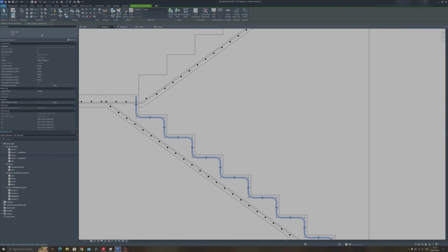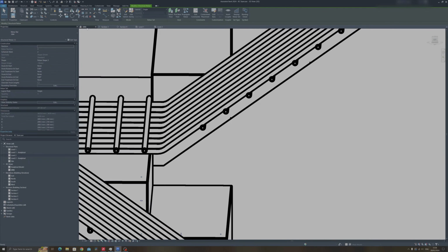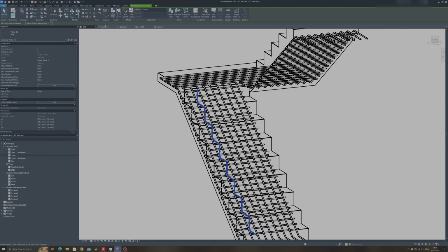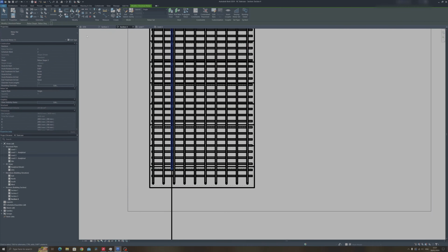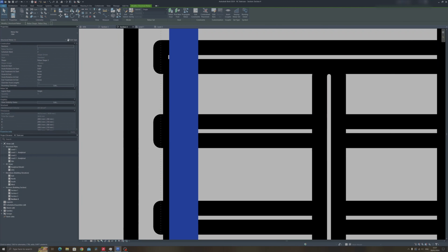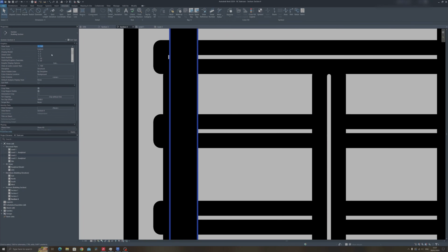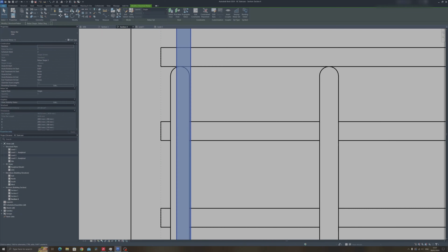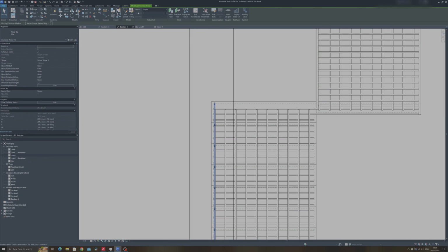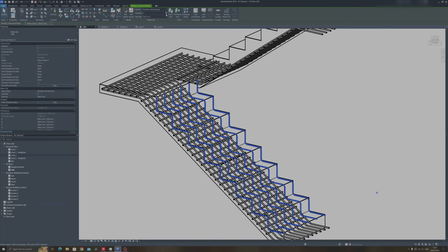So we can actually use a smaller diameter, let's say 10mm rebar. Just the view visibility. Proceed to section 4 over here. And let us move it to where this rebar is over here. Best to use finer scale. And then choose number or spacing. You don't really need it to be too close to one another over here. Let's increase it to about 5 over here.